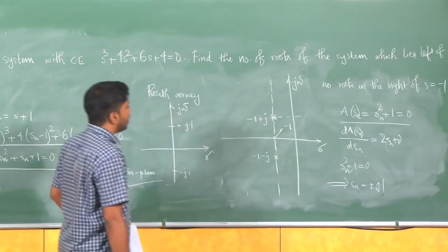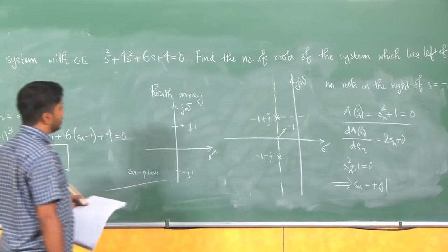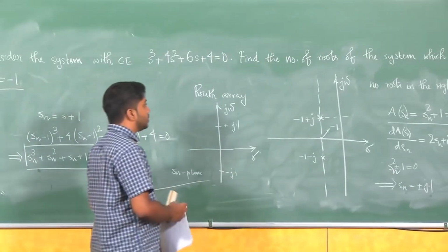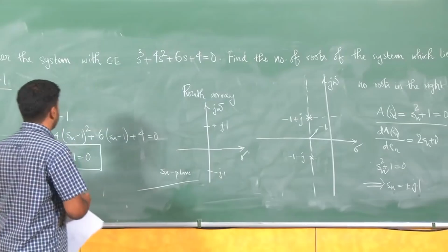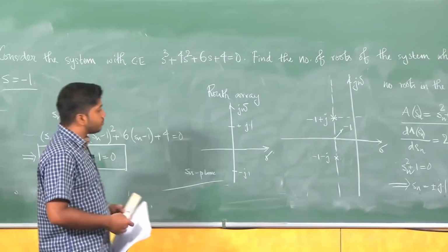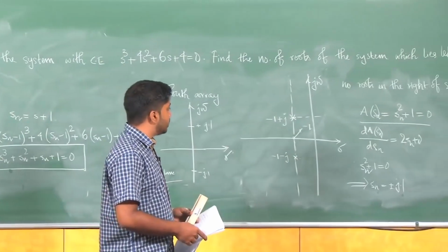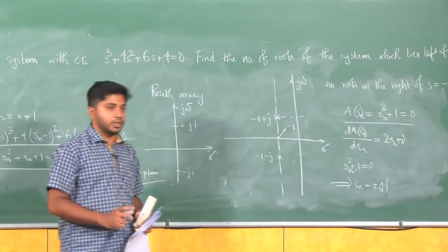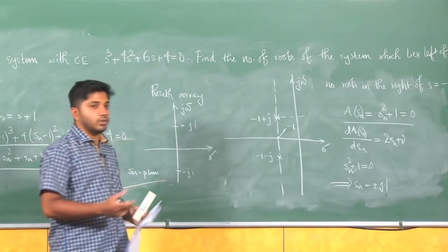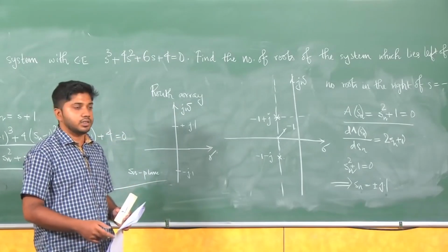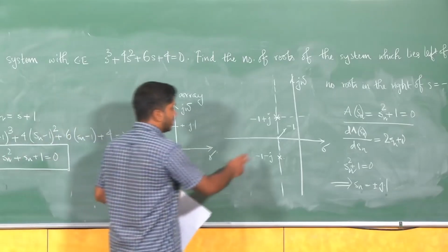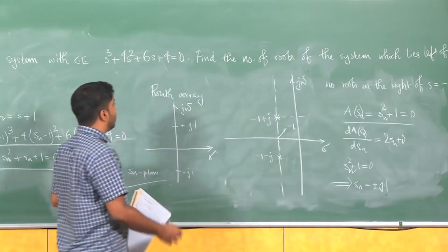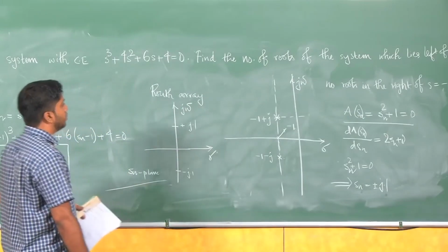So, this kind of axis shift is very useful in systems where there are a number of complex roots, so more than one complex pair of roots. If we are going to determine the relative stability of the system based on how the roots affect the damping of the system, this axis shift method using the Routh-Hurwitz criteria will be helpful.